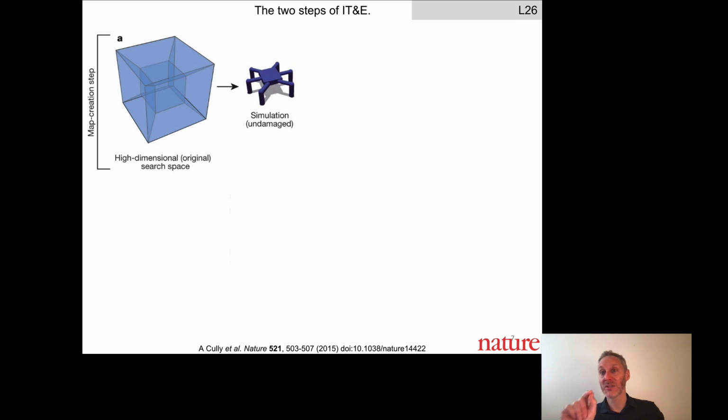We can ask, what's the fitness of each of those controllers, which is our vertical axis. If we have a controller, like from a Braitenberg vehicle, remember the Braitenberg vehicle had pairs of crossed and uncrossed wires. A controller for a Braitenberg vehicle is described by two numbers, the weights of the two synapses. If we set those two synapses as our two horizontal dimensions, then any point in the horizontal plane corresponds to a particular controller. And the height of that point, again, is the fitness of that controller.